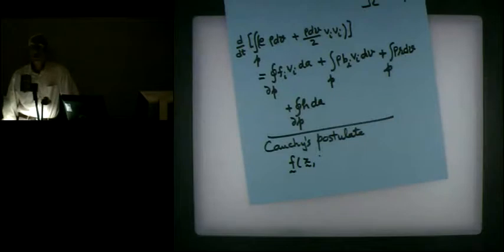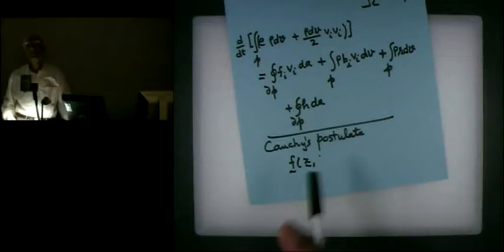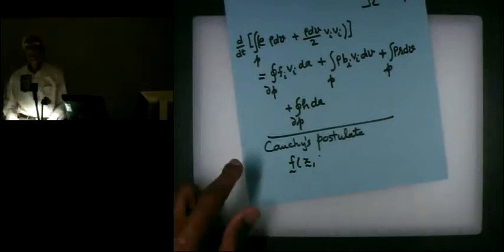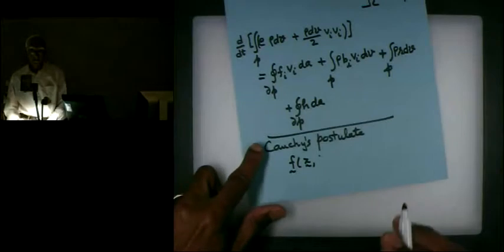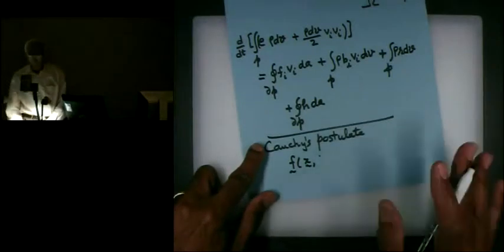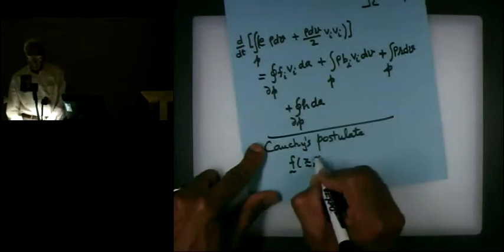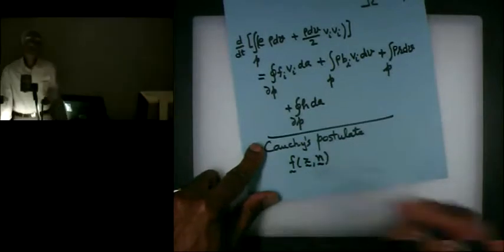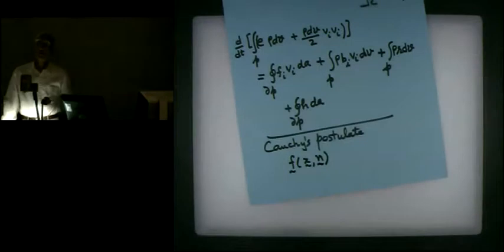It only depends on the point of action and the outward normal. So the surface tractions depend upon the orientation of the surface only through the outward normal.